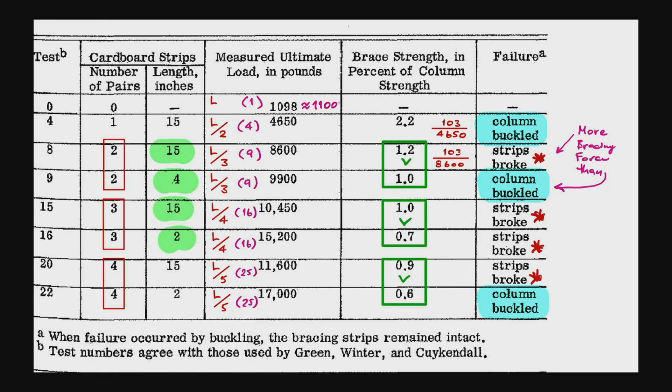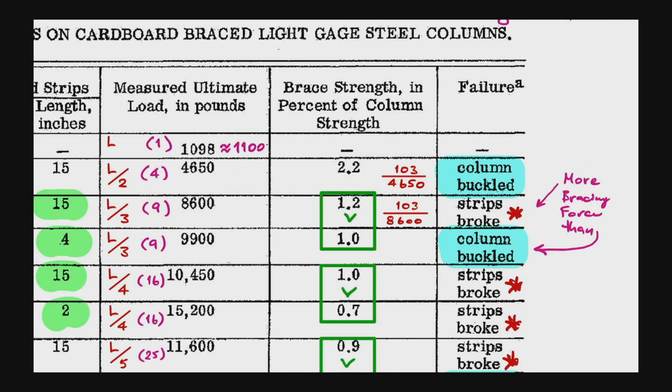Okay, and then we can see this figure here, that the case where you have less stiffness, you have the higher bracing force ratio compared with the capacity, right? Bracing to column capacity ratio, it is higher than this counterpart.